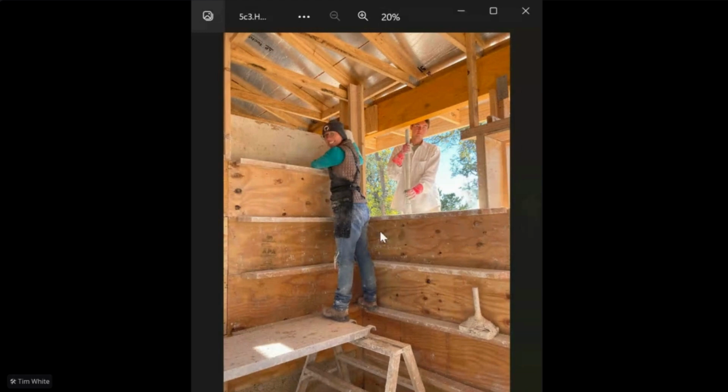This slip form here, all of these slip forms, actually, they only have one screw at the top here and one screw at the top on the corner, and they lock in on the bottom. So to move a form, you're only taking 2 screws out at a time instead of 4 or 5 or 6 or 8 or 10.